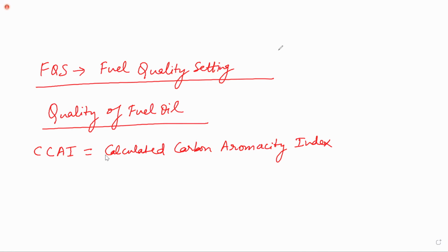And when my ignition does not start at the same point where I desire it to start, my combustion characteristics will change. So that is why the fuel injection is advanced.